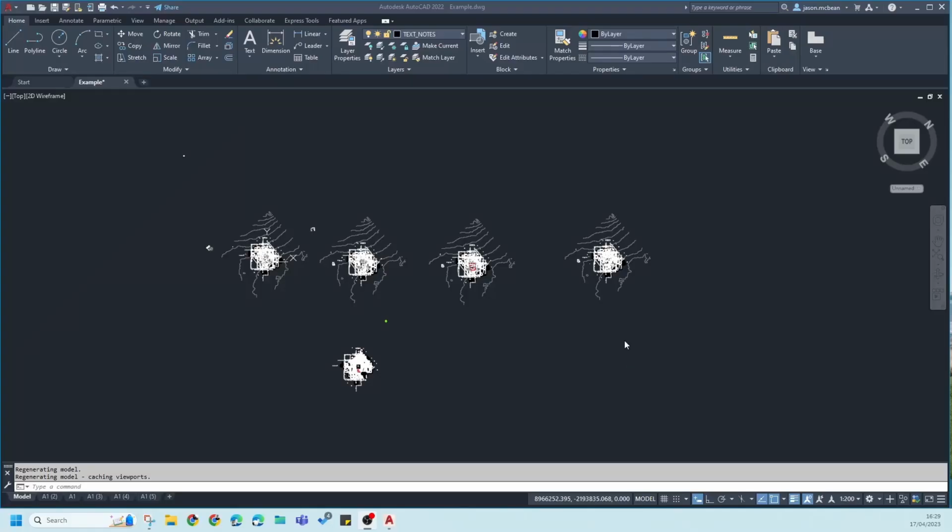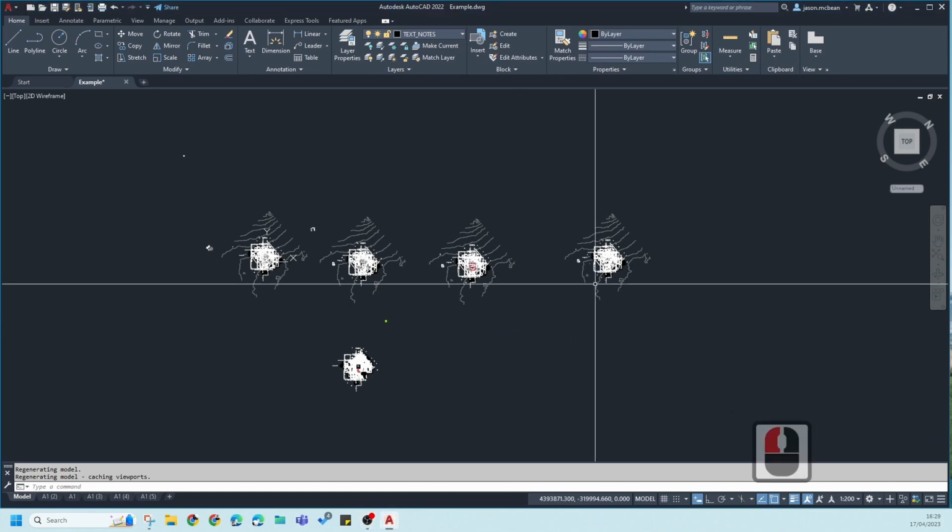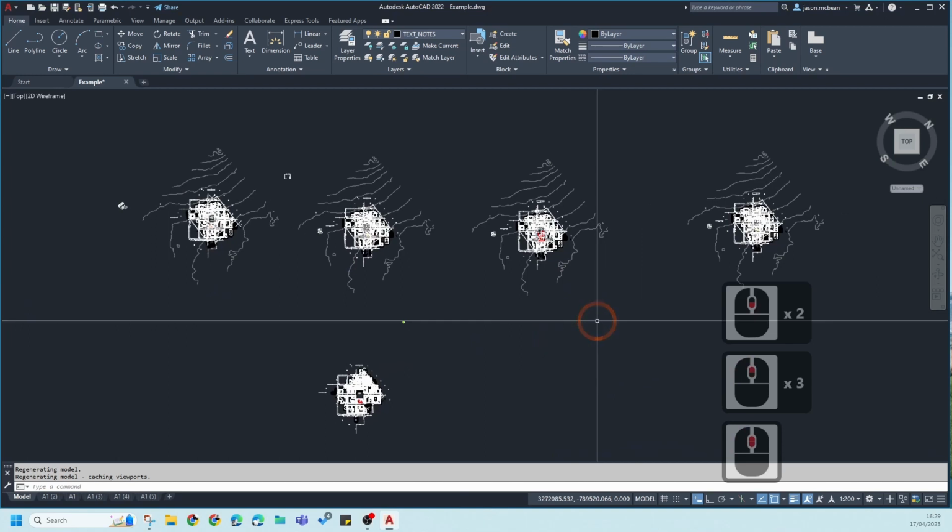In this tutorial, we're going to cover how to extract the correct site information from your DWG files that you've been creating. We're going to extract just one site plan that we're going to use to help us develop our Revit site plan project. In essence, all you need to do is remove all the unnecessary information in a drawing and then save it as a different drawing that you can keep cleaning up, that you're going to be linking into Revit.